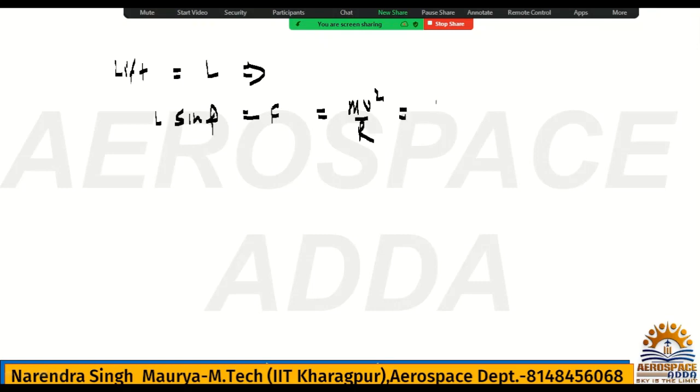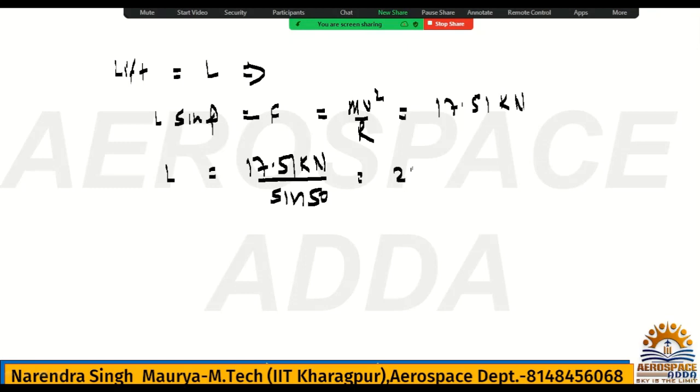It is 17.51 kilonewton. So what will be the L? L is nothing but 17.51 kilonewton divided by sine 50 degree. So you just divide by sine 50 degree. It is nothing but 22.86 kilonewton. This is the value of lift.